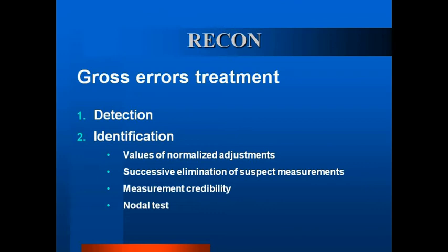In the case of mass balance, the imbalances around individual nodes, or their combinations, can be statistically tested. It is called nodal test. Streams around suspect nodes are suspect. This method is suitable also for finding the frequent model errors, such as leaks, or neglected mass accumulation. Covariance matrices of adjustments are available for detailed analysis of the gross error identification problem. The steps in gross errors identification are semi-automatic. All this serves as a decision support system for the user.